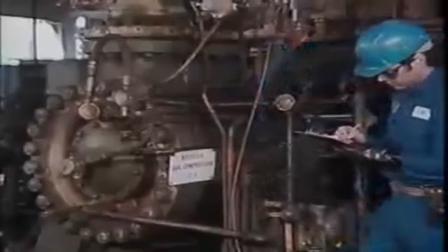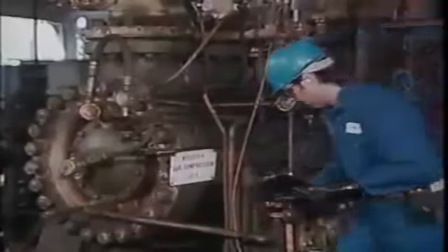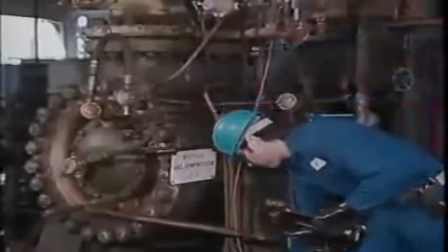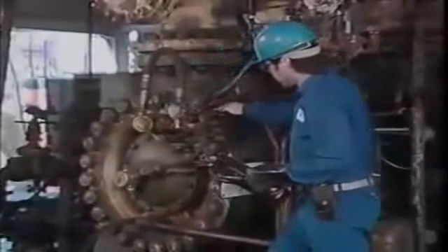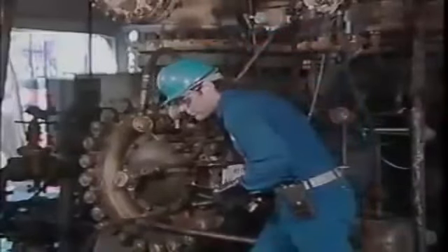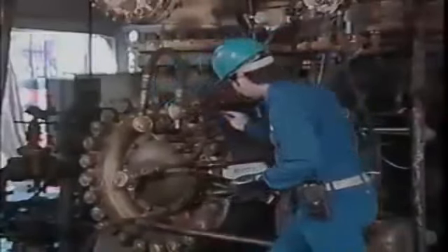When you're checking a compressor, remember that it operates at a very high speed, so be extremely careful when you're working on one that's running. An important part of checking an operating compressor is listening for unusual sounds. Most compressors produce a high-pitched hum when they're running. An unusual raspy or squealing sound can indicate a problem with a bearing.